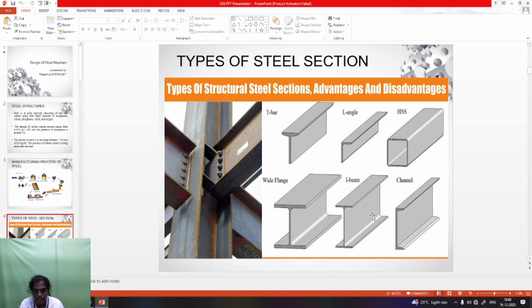Okay, so this is the I section. The I section is normally defined by very wide flanges; this is a normal I section, and this is the wide I section. Next is the C section. C section means channel. The channel section is also a beam structure. It also consists of light, heavy, medium and wide. These four categories are considered in Indian Standard Code IS 800 2007. So these are the types of steel section used for workshop buildings or any type of railway platform.